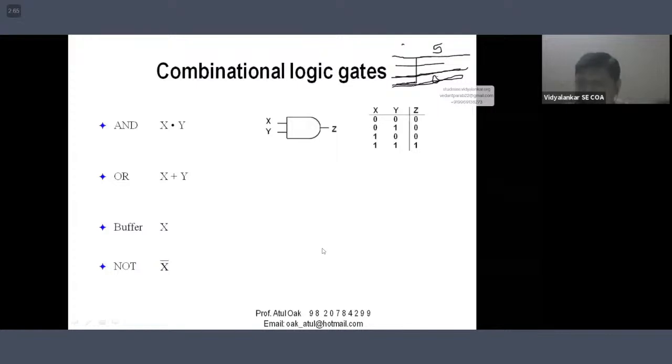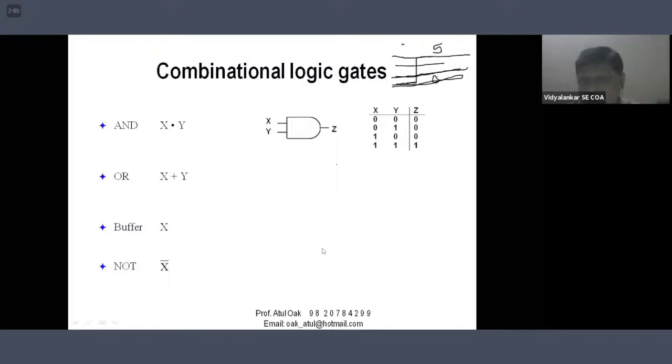So basically when you talk bits, you talk voltage, please remember. When you talk bits, what you talk about is either a slightly high voltage like +5, which is a big 1, or a low voltage, ideally 0, that is a big 0, but practically there is a range. We do not talk about a specific value, we always talk about a range of values. So if my voltage is 4, then it is logic 1. If my voltage is 4.2, it is logic 1. If my voltage is 4.8, it is logic 1. If my voltage is 2.5, then it is neither 0 nor 1. We will not discuss that now because that is a totally different story. We will only talk about 0 and 1.